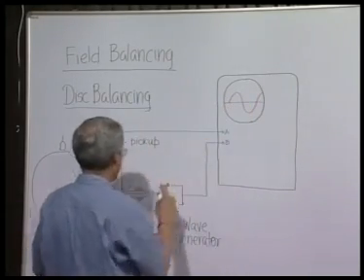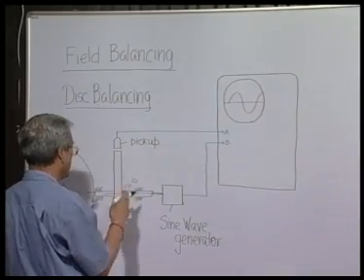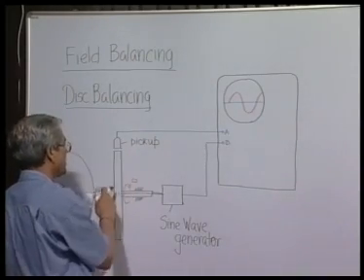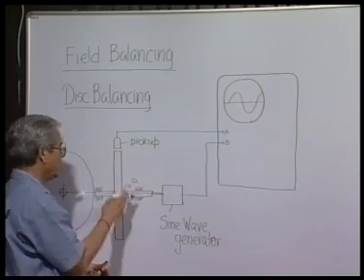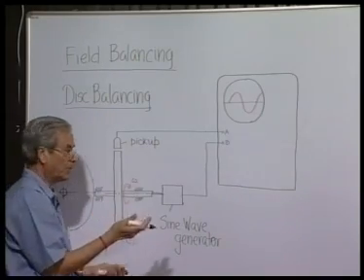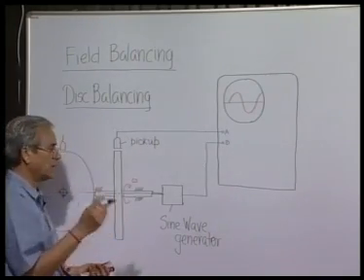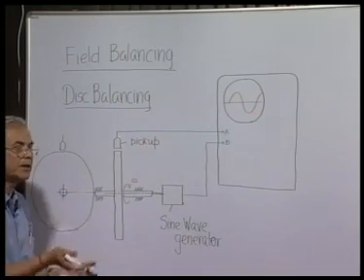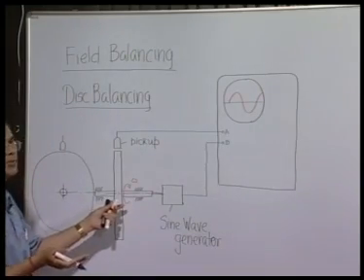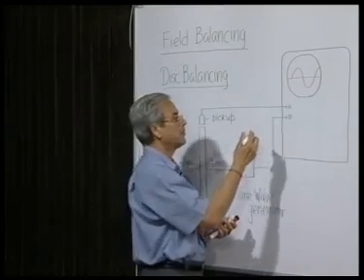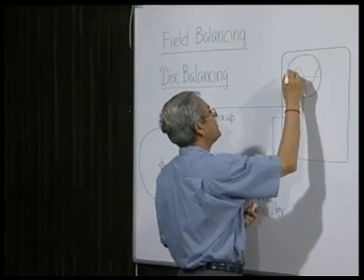Remember, in steady state the frequency of this vibration will be the same as the speed of rotation, because the exciting force is nothing but the centrifugal force generated by the rotation. So, they will have the same frequency, but they need not be at the same phase.